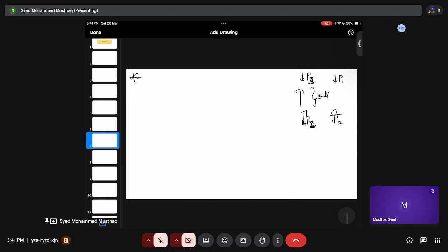Now, what are the disadvantages? Again, there are other trends also that have been followed. Instead of just using carbon dioxide, people are trying to use methane also. What this does is that methane will react with your oxygen to give 2 moles of carbon monoxide and 4 moles of hydrogen.